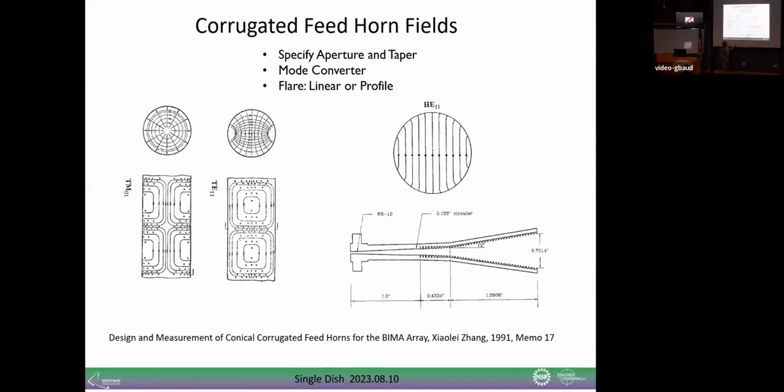And the other thing is the length of the feed. It's primarily the taper. The concept of tapering the feed pattern at the edge of the dish to some optimum value is mostly controlled by the length of it, and that gives you the gain and the taper. So those two factors are what determine the illumination of the corrugated feed.